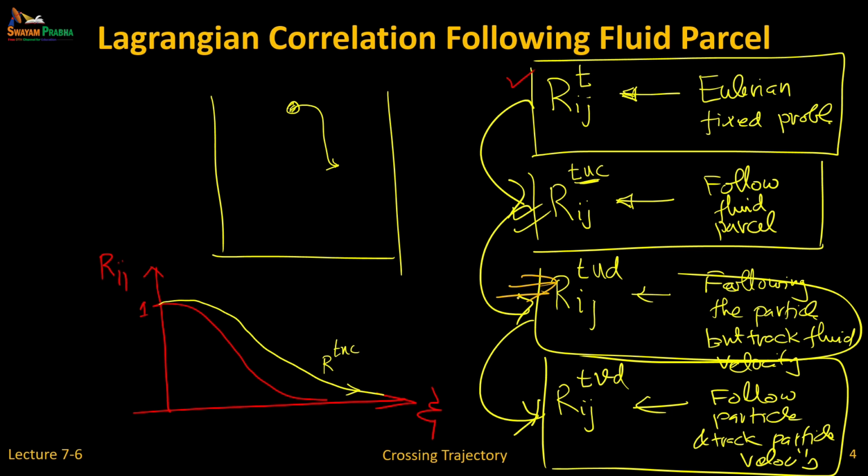So how far will I get? Close to red or shorter than red? I don't know. It depends on the problem. But all I know is that the new one that I'm going to draw is going to be less than yellow. How much, I don't know. So that's an interesting effect for a Lagrangian particle. Now when the Stokes number of a particle is very small, the orange one and the yellow one will be similar because it's just tracking the fluid.